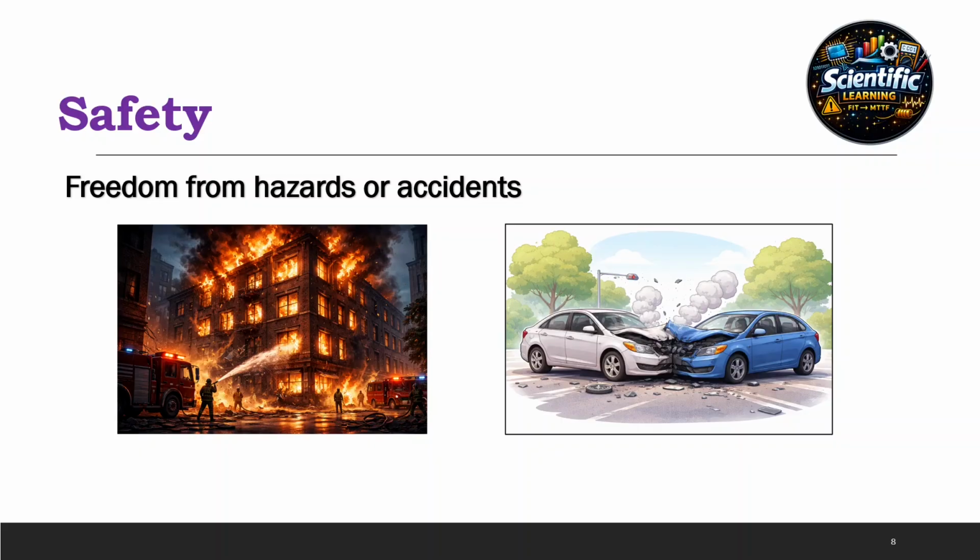While reliability and availability are expressed in probability, simple probabilities, safety is expressed in probability of failure on demand. We call it PFD. That is, it looks at what is the probability of a system to fail when there is an actual demand on the system to take a safety action.